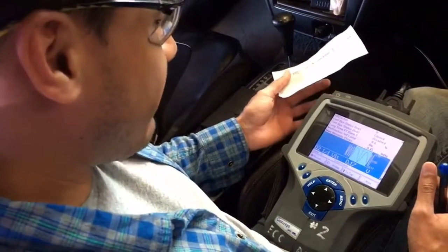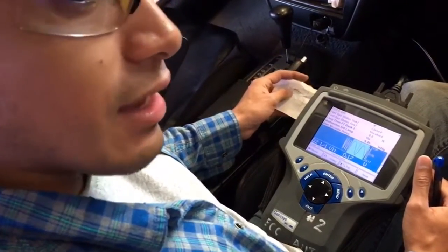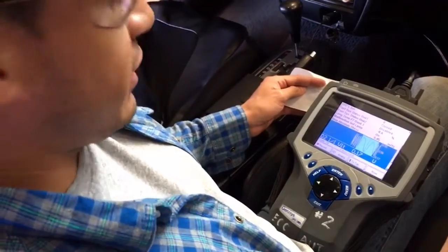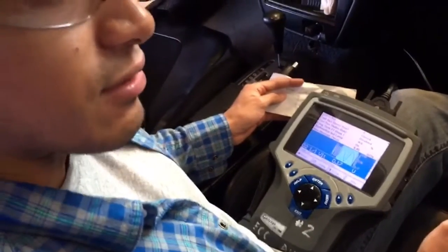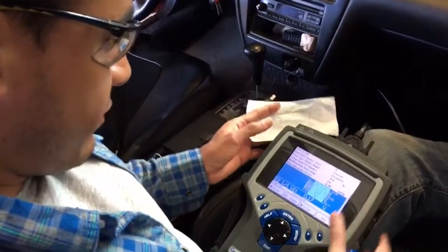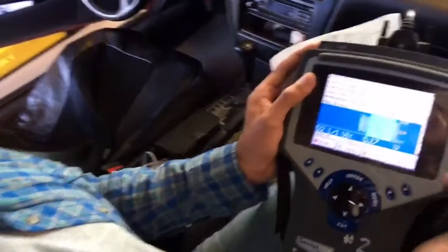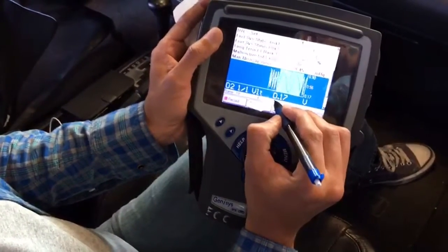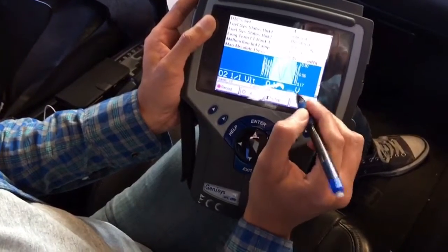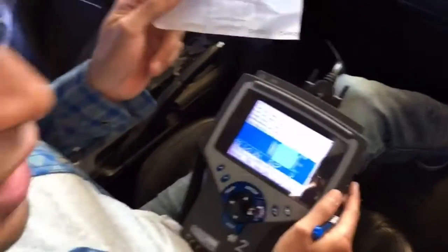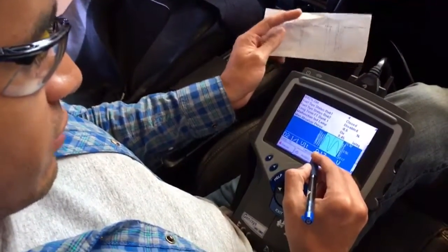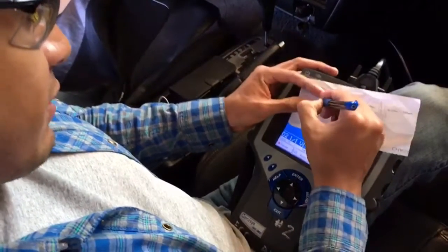Alright guys, right now we're going to test an oxygen sensor. We're doing the upstream. So basically what we're checking for is voltage. Voltage signals have to be at a certain point, so what we're going to do right now is check. As you can see here, we want to move the decimal point over 1, 2, 3, so it'll be 170. Right now it's set in volts, and what we want to check is millivolts. So right now it is 170 millivolts. I'm going to make a tally.